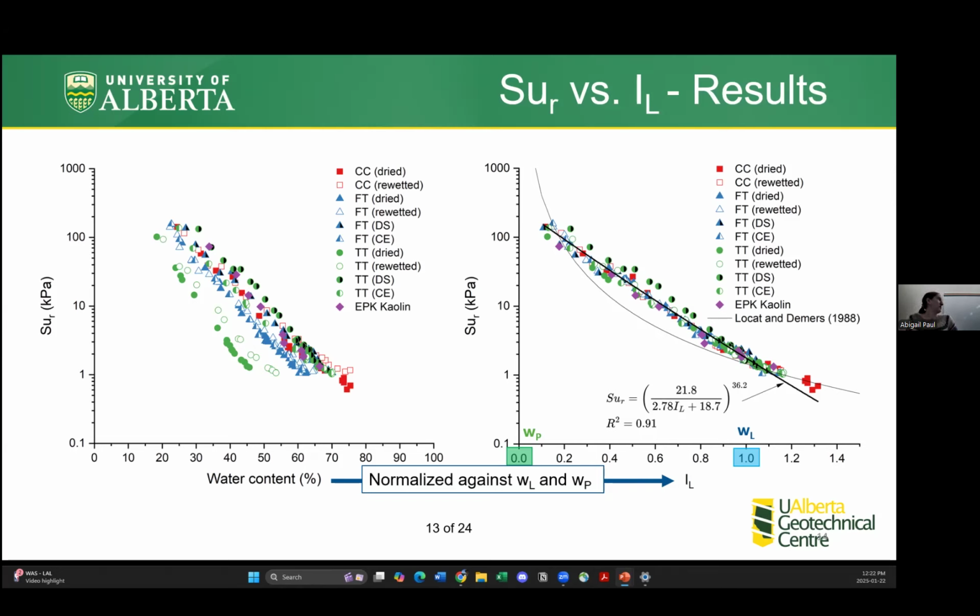I will take a moment to add some complexity to this though, because you'll recall that just a few slides ago, I was saying that Atterberg limits are not super reliable, they're very variable. So while this relationship is an easy way to estimate strength properties from index properties, it is an estimation, and actual strength measurements are always going to be more appropriate than something like this.